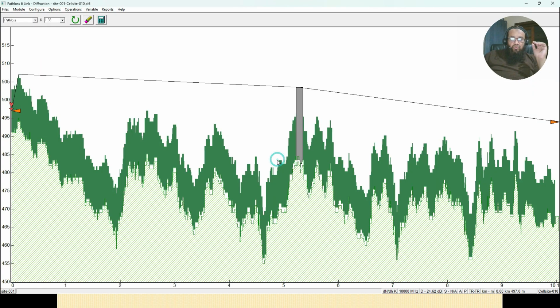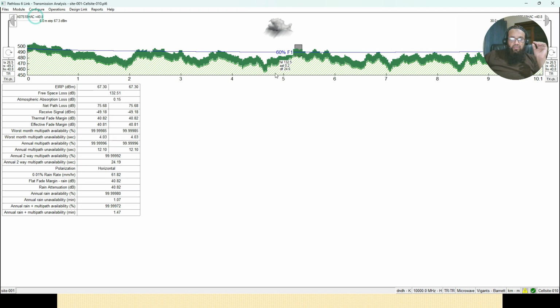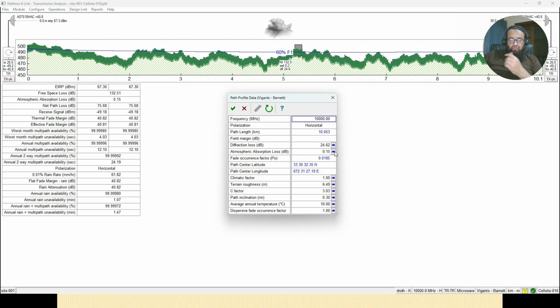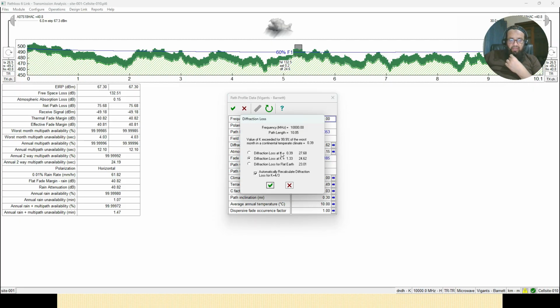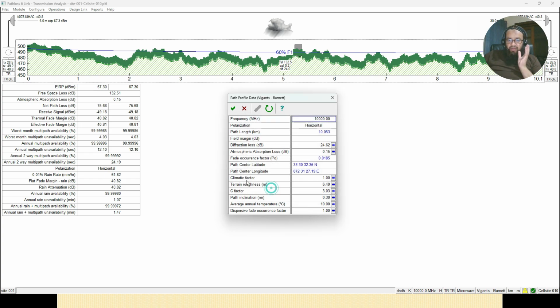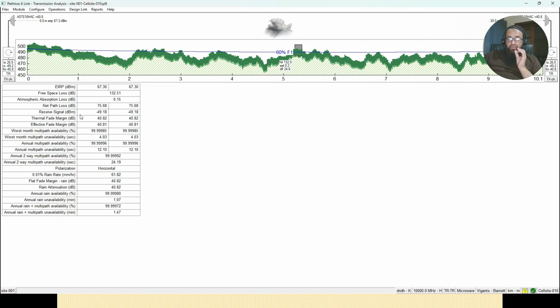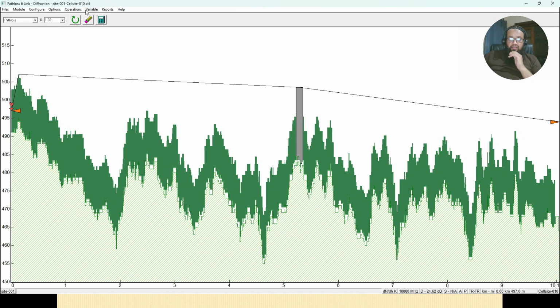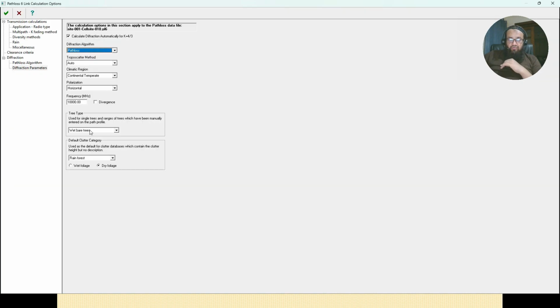If you remember here, let me take you again just for a moment. You saw here also that even for this value, if you change the k value to different things, the actual value changes. So what I wanted to say is that everything will change your values. If you change anything from here, it will have some kind of effect on the final value. For example, if the foliage is wet or dry, we know that the dry foliage has low loss and the wet foliage has a bit higher loss.